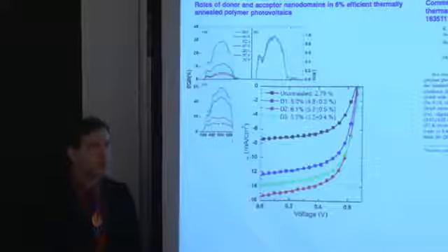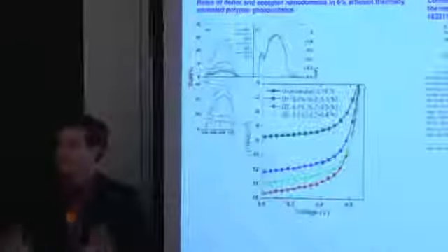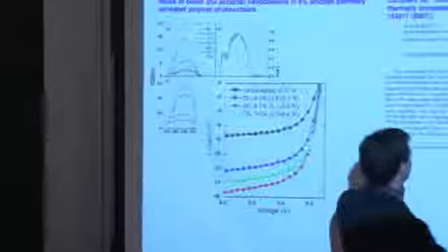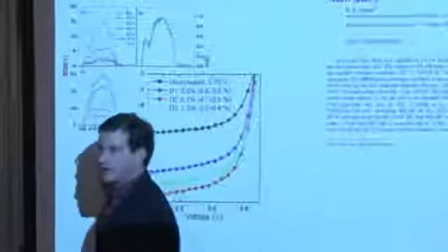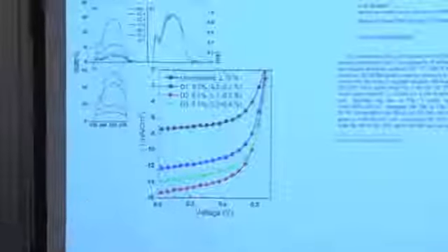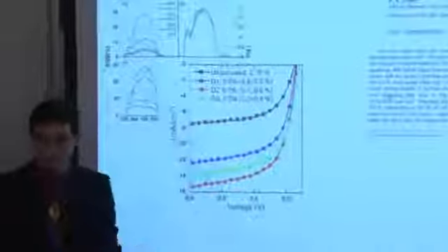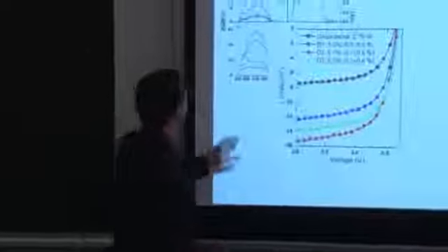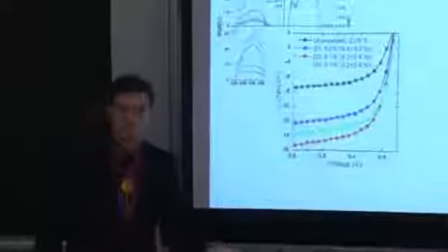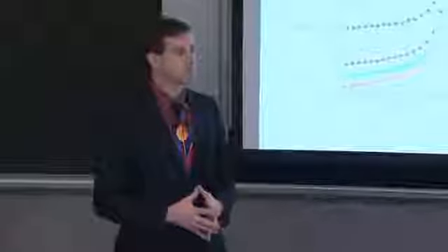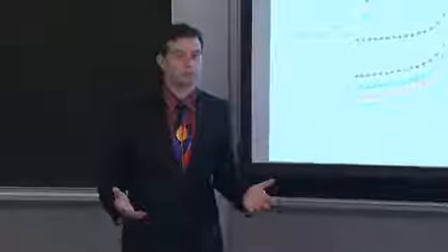Well, guess what? Folks at NREL also know how to do that calculation, and a whole lot more. So the folks at NREL did that and said, well, wait a second. When I do the integration of your QE, I'm not getting these short circuit currents over here. I suspect what happened was in your solar simulator, you were using a silicon reference cell, but your cells were more sensitive to a different region of the solar spectrum. In this particular case, they were more sensitive to the shorter wavelengths, and you didn't have a properly calibrated solar simulator. So you're over-reporting your current outputs.